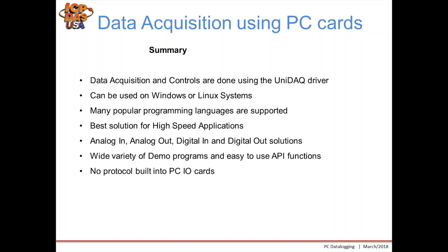We have a wide variety of demo programs showing everything from how to monitor the status of the inputs to controlling the outputs. And the easy-to-use API functions are available in the API manual for that specific board. And again, there's no protocol built into these boards, so you can't just communicate by Modbus to the board. You need to actually create a program for these.